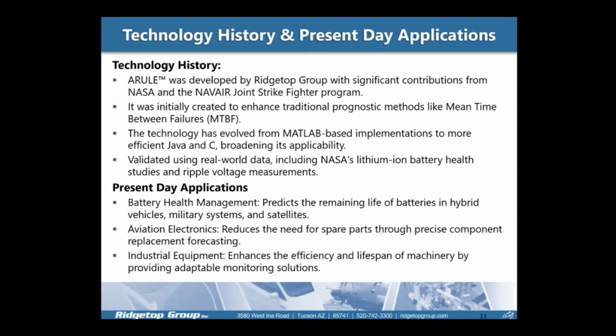And then we also have several industrial IoT applications where we look at doing vibration analysis or time domain analysis on certain gearbox systems or bearings and wheels, such as that in the railroad industry, to determine the state of health and remaining useful life of those key systems and subsystems that we're trying to monitor.